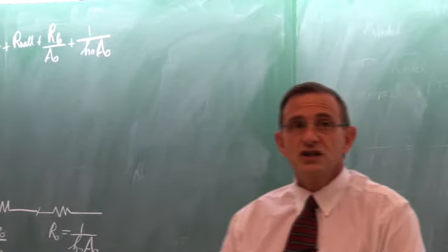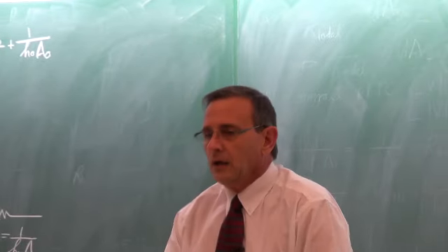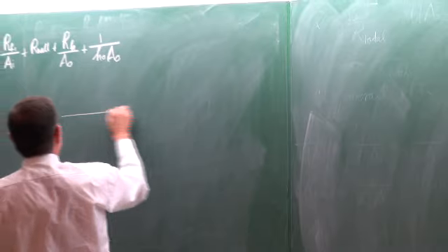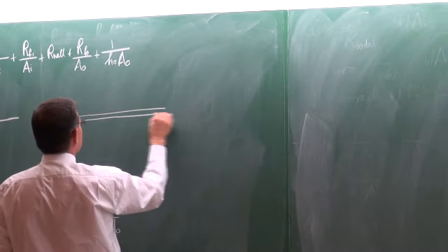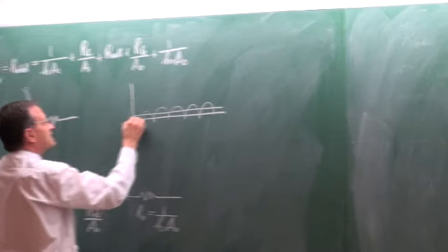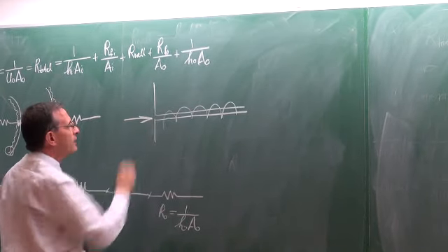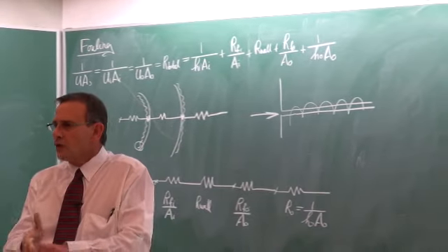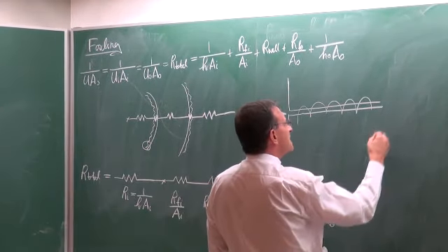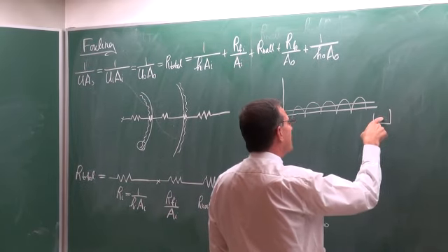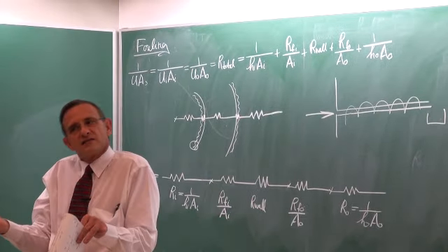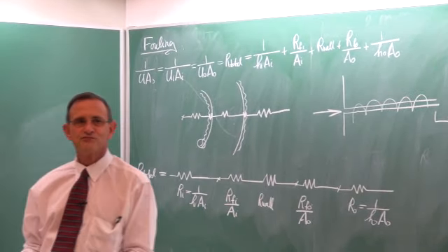A few years ago, I was involved in a project where we had a very, very simple experimental setup. It was just a tube which was being heated, and we had some of the municipality water flowing through it over a period of a year. Then we could determine this resistance by very accurately measuring the mass flow rate. As the resistance increases, the mass flow rate must obviously decrease.